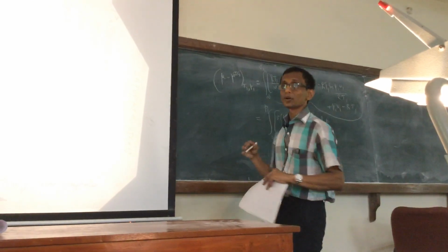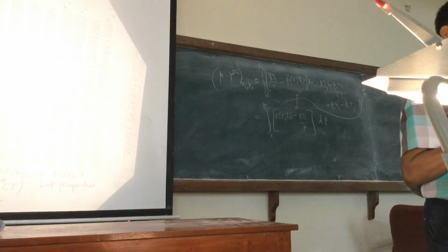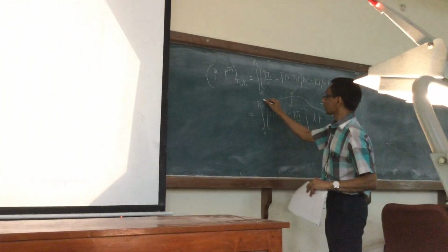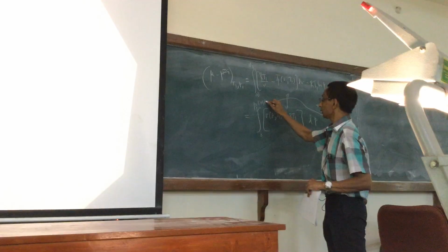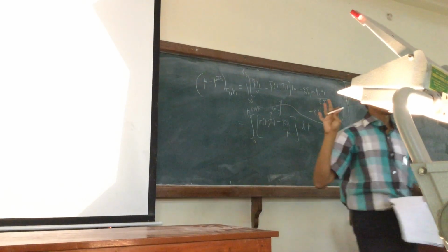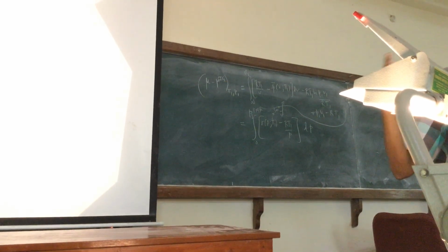Now this is what he wants you to use to calculate the fugacity. So P1 is given now, 8 megapascal, T1 is given, 300. So we have to go to the superheated tables. For 300, superheated will be in terms of pressure as well as temperature.